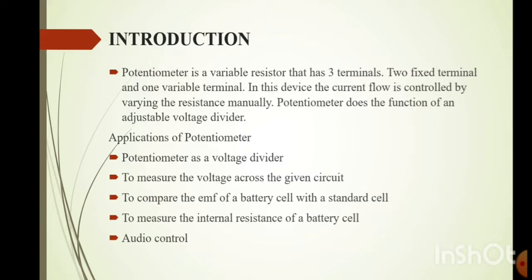Applications of potentiometer. A potentiometer can be used as a voltage divider to measure the voltage across a given circuit, to compare the EMF of a battery cell with a standard cell, to measure the internal resistance of a battery cell, and for audio control.